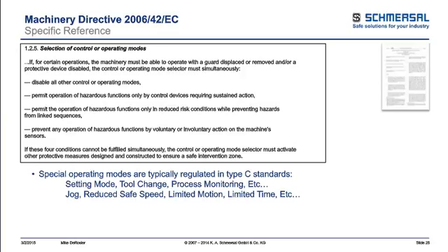In doing that, when you look at another reference in the machinery directive, they're talking about how some of the conditions cannot be fulfilled simultaneously, such as special operating modes, which are also active in Type C standards. So robotic, being able to teach. Do you have a setup mode or a tool change mode? Those Type C standards call out the additional protective measures that have to be activated during those modes, and you want to have that clearly defined and ensure they're put into place.